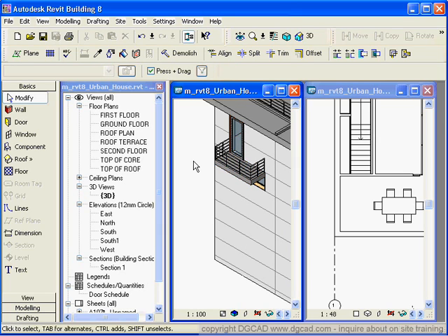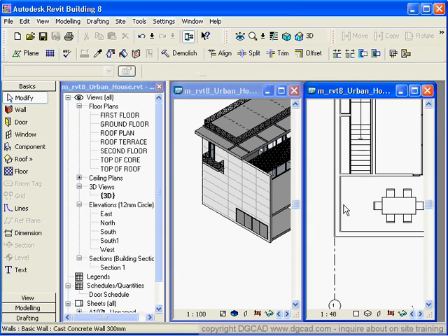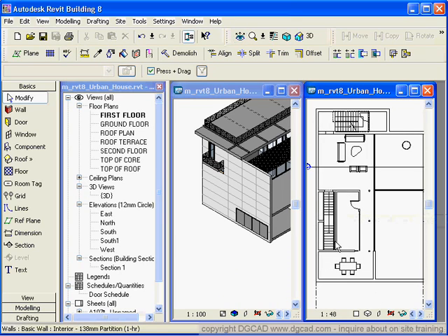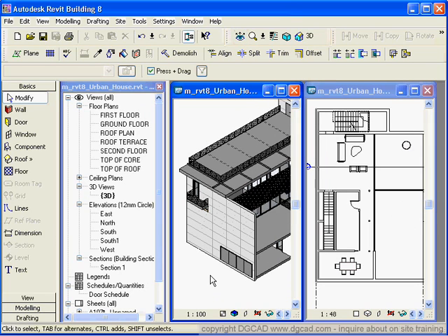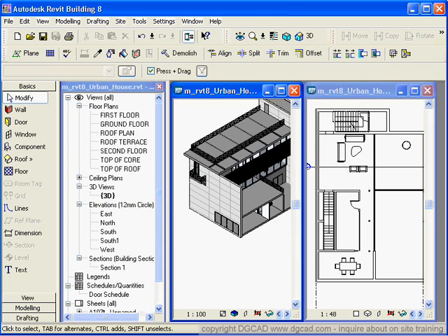And then we've got different objects, and so I'm just really talking about the windows here and the fact that you do have different windows, and we have some shortcut keys. SD will give me a shaded view, and HL will switch that back. Similarly here, HL will give me just a hidden line view. SD gives me my shaded view. So we've got our different views inside of here, and they update accordingly.